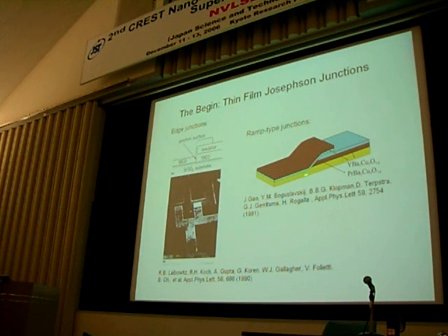And what you can do then is put a base electrode, cut very flat as a ramp for the structure, and deposit praseodymium-barium copper oxide epitaxially on it. Praseodymium-barium copper oxide is non-superconducting. And here on top, yttrium-barium copper oxide again. That means if you have c-axis orientation, all the superconducting copper oxide planes are horizontal, and then we get direct coupling through. And it turned out that it worked very well.